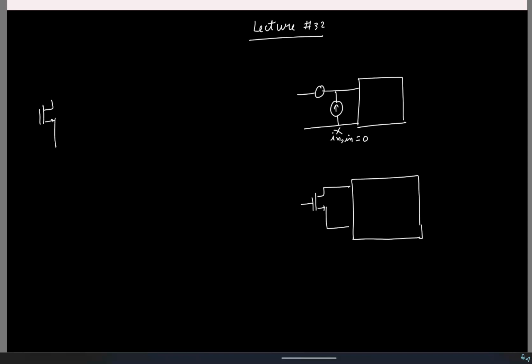And also for a MOSFET, although the noise in the drain current is ideally modeled using a parallel current source, we saw that if we don't consider the gate capacitance, which translates to having infinite input impedance, this noise can also be modeled using an equivalent voltage source at the gate. So the drain current has a power spectral density 4 kT gamma gm. So this will have a power spectral density 4 kT gamma by gm.